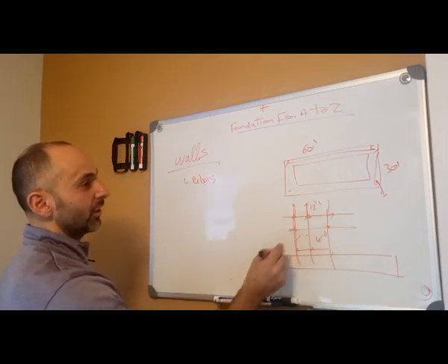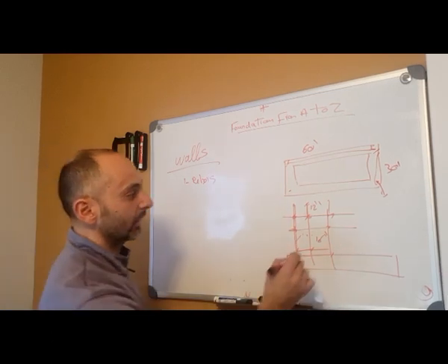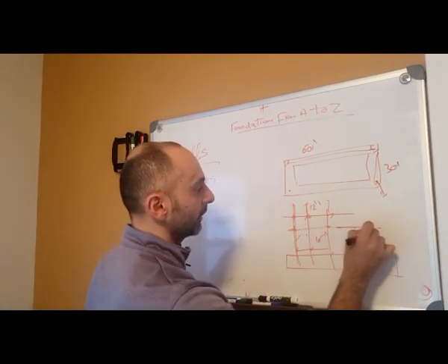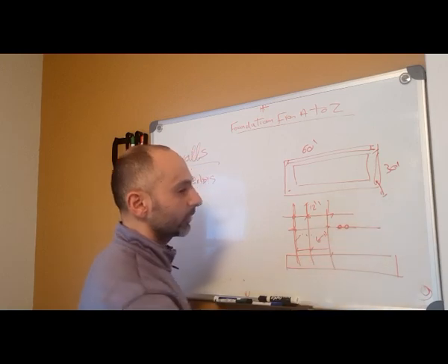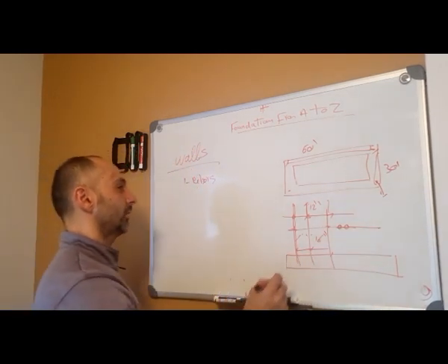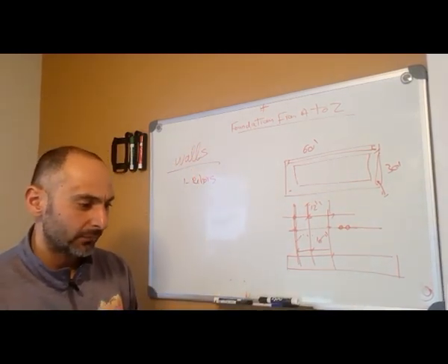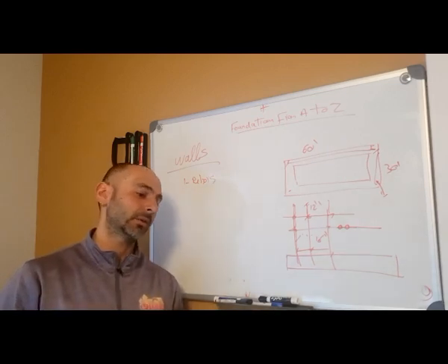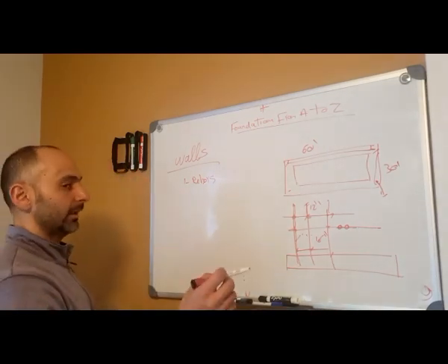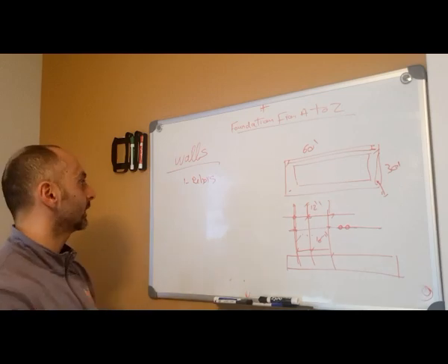So make sure this is a neat job. Make sure all overlaps are good. If you have two overlaps, make sure you tie the old bar with the new bar. Make sure you have 30 inches. I think the rule is 45 times the diameter of the rebars. Again, this should all be from the plans.